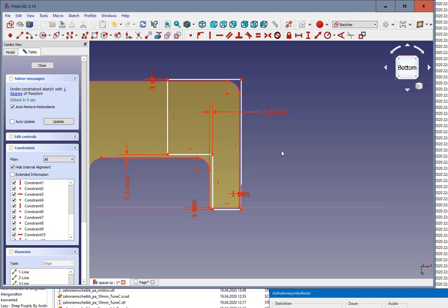Why not 1.5 or 1.7? Well, the reason is my printer does 0.4 wide lines, and then it's 4 lines, and it's easier to calculate and it's easier to maintain the 1.6 millimeters than 1.5 millimeters. So that makes some sense for the 3D print afterwards.